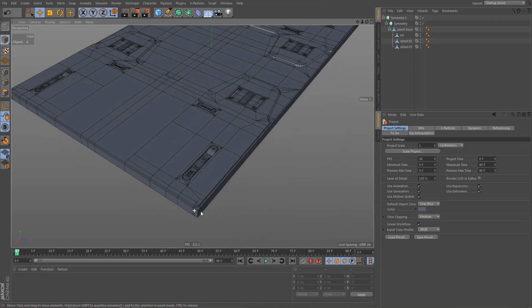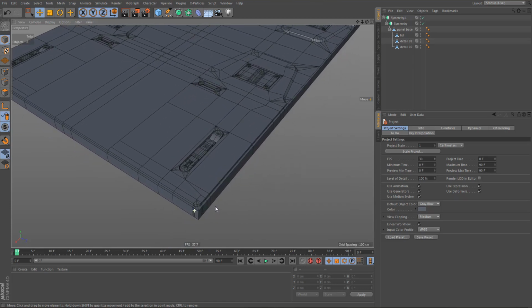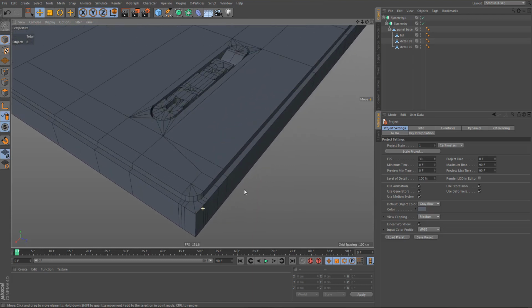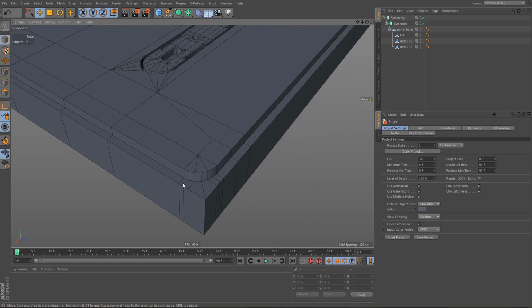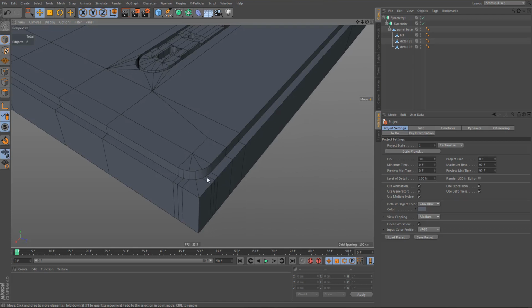One thing I told you in the previous video was actually not quite true. I told you that we will get problems when we try and use a bevel deformer on poles, but we can actually do that, and I don't know why I didn't think of that in the previous video. We can use some settings in the bevel deformer to make those bevels work on poles as well. And one example would be the corner of this panel base.